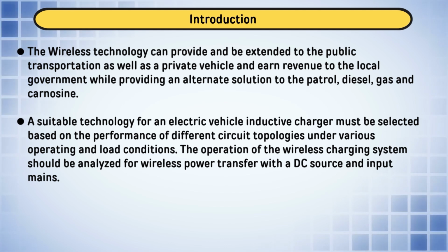For extracting the maximum power from this renewable, we need this DC converter, and as this PV module is acting as a source, only a unidirectional DC-DC converter is required for extracting the maximum power.